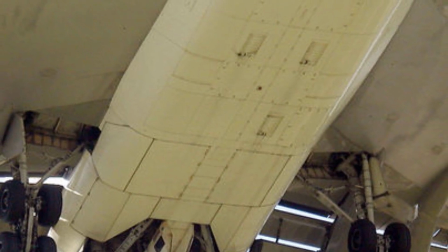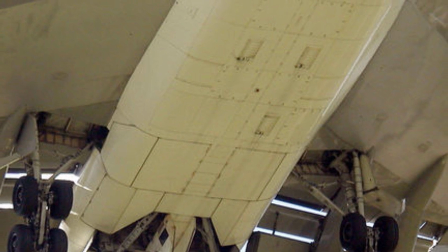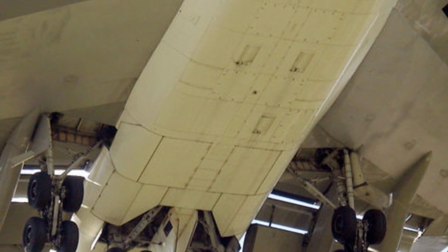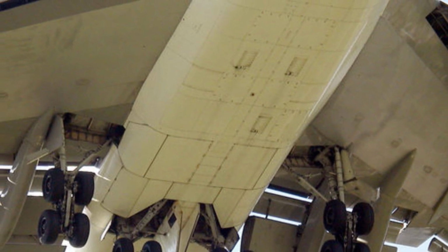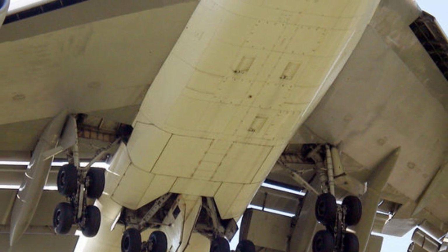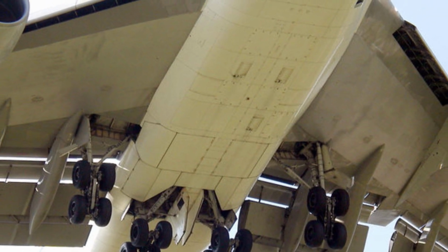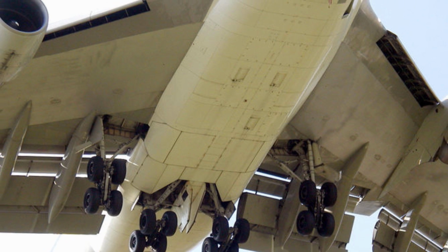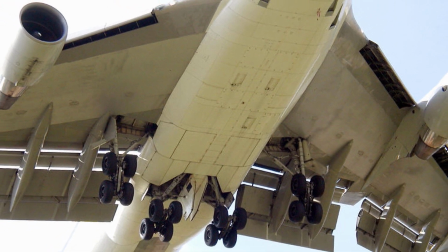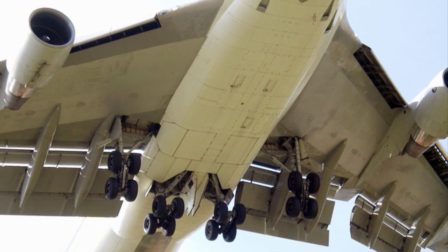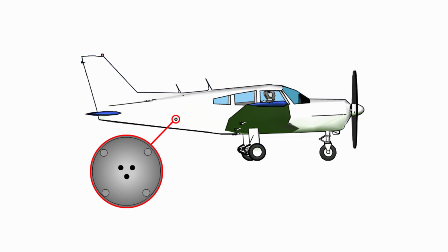Changes in aircraft configuration like deploying flaps, slats or landing gear will also have an effect on pressure head system reading. Deployment of these surfaces will change the angle of attack, thus increasing turbulence around the pressure head system. Position errors are determined during aircraft flight test and tabulated in the flight manual. The usage of a static vent instead of a pressure head can significantly reduce position error on static pressure reading.